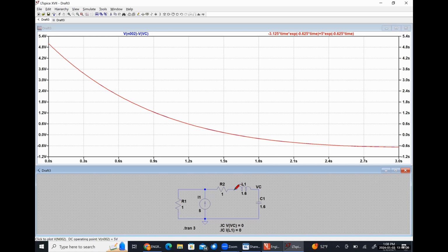So we're having to explicitly give it 2 points because our inductor isn't measured, like one of the terminals isn't at ground. So if we just did this node right here, it would actually be the voltage drop across the inductor plus the voltage drop across the capacitor, which isn't what we're exactly looking for.